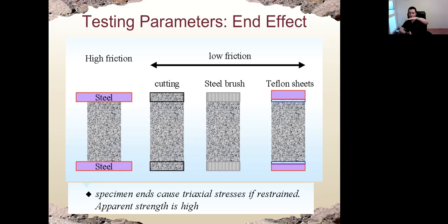So the friction provided by the top and bottom steel plate is very important, because if the friction is high, it will try to constrain the concrete from further expanding, preventing the concrete from cracking. Actually, the concrete cracks because of the tensile stress due to expansion in the horizontal direction, not because of the compression.